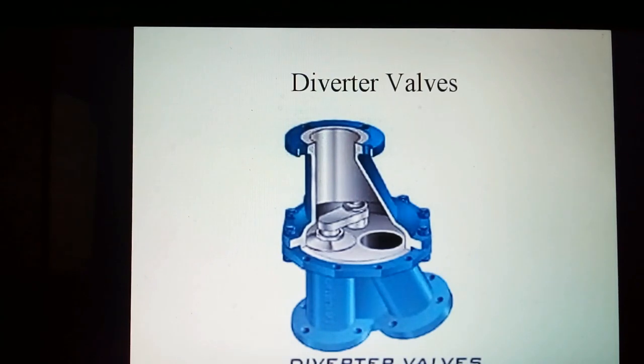Diverting valves. Two types of diverting valves are made. Both switch flow from a line inlet to one of two outlets. One type is a Y pattern, which has a hinged disc at the junction which closes one of the two outlets, and is used to handle powders and other solids. The second type handles liquids only, and has no moving parts. Flow is switched by two pneumatic control lines. It is available up to 150 mm in size.